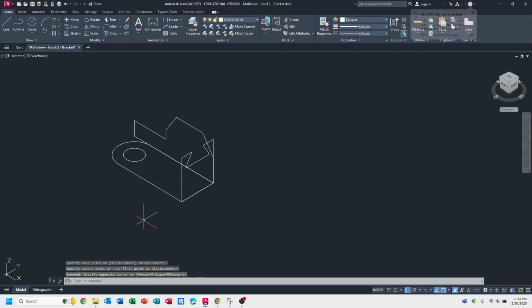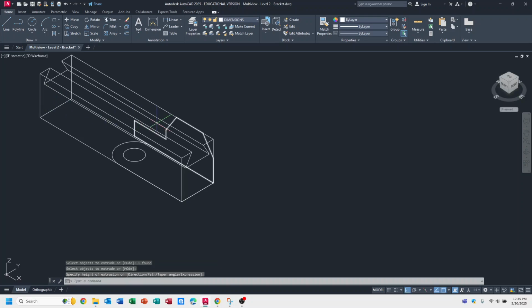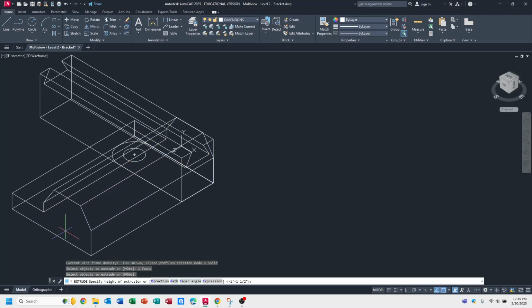So the last step that we're going to do to build our 3D is the intersect command. So the first step for this, because it works on boundaries, basically with the line intersecting, and it will remove anything else, we're going to extrude these objects through each other. So EXT enter, pick your object, and extrude through. So same thing, EXT enter, select your object, and extrude through.